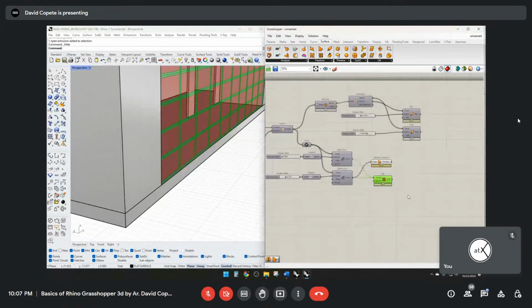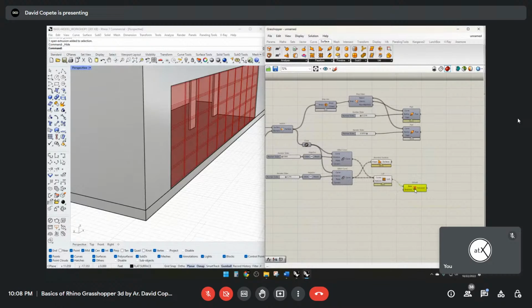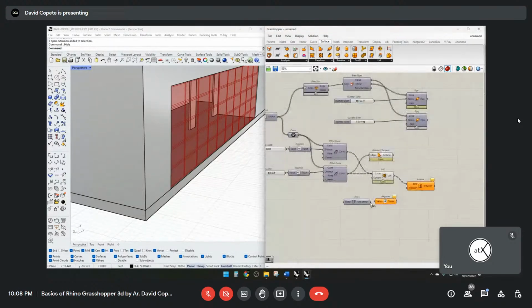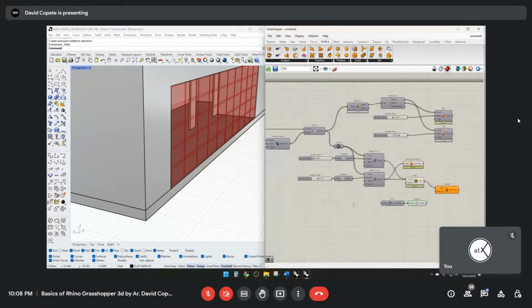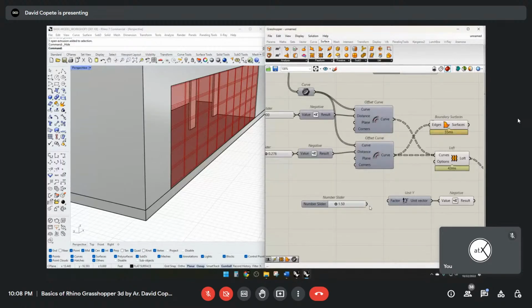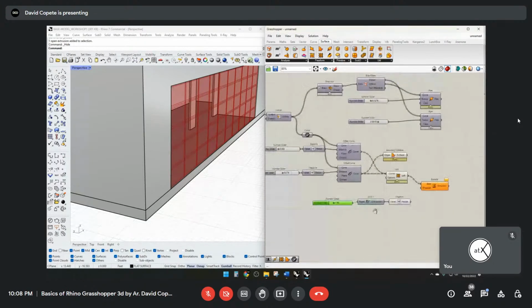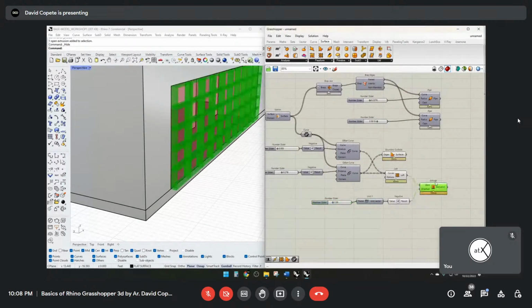So we'll take this, we'll go to extrude. And when we look at which direction we want to extrude, I look at this widget down here. There's the X, Y, and Z. We're going to be extruding it in Y, but negative. So I'll go here to unit Y, bring in a negative component. Now we'll give it a value of, say, 1.5. A little bit too much.